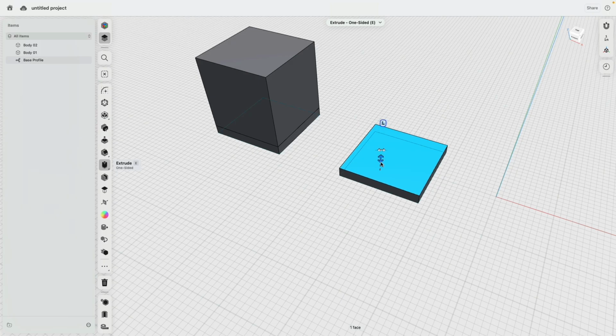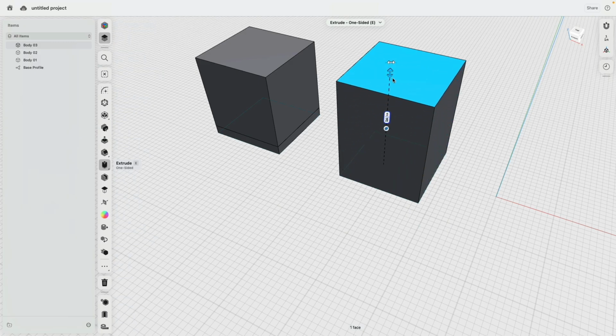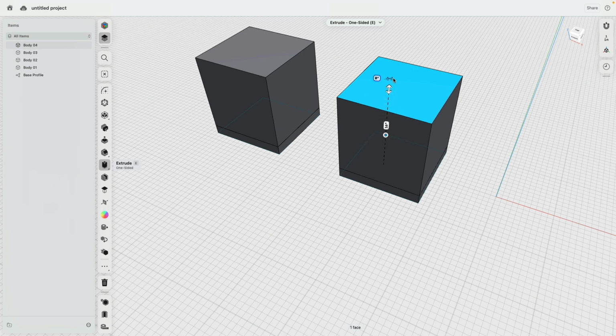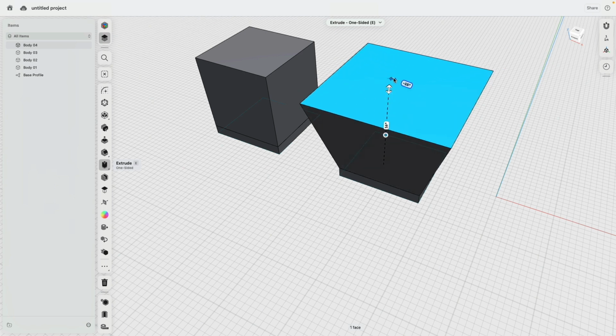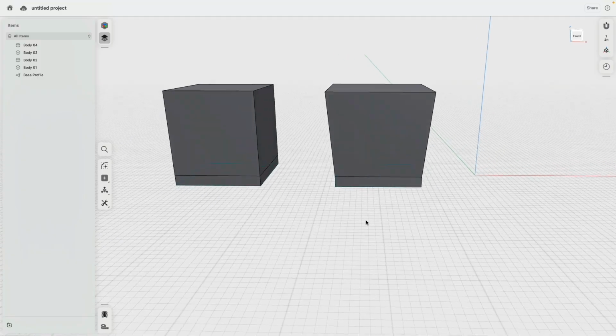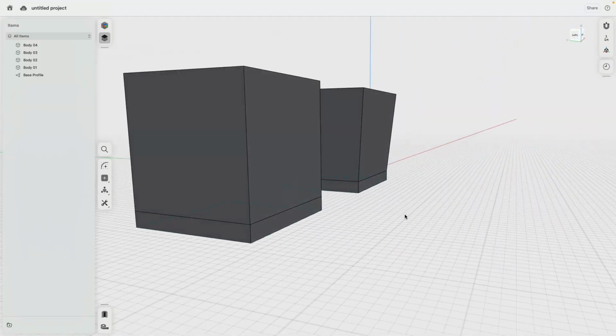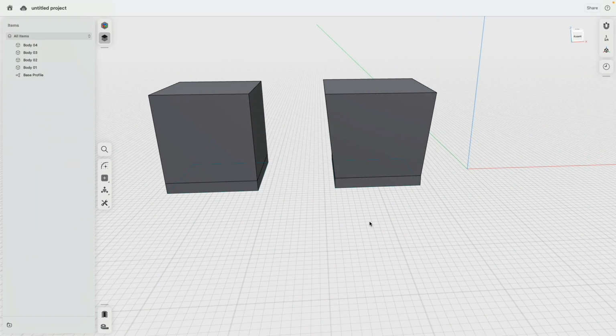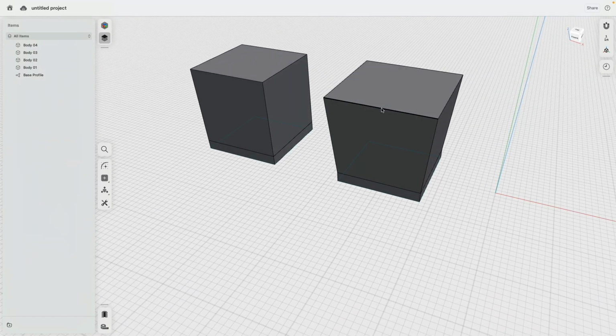Here we do another 2 inches for the extrusion. Let's do a little bit of repetition. Another 16 for the extrusion, new body. But now here we're going to change the degree. 5 degrees, fine. Now look at that. Now we have a nice kind of like tapered base. This is actually now also a little bit bigger now because we angled this.